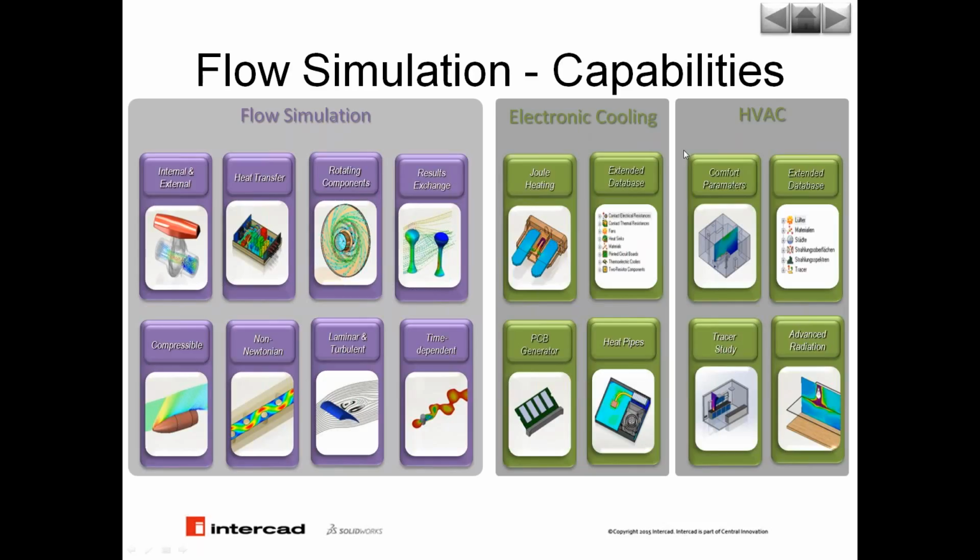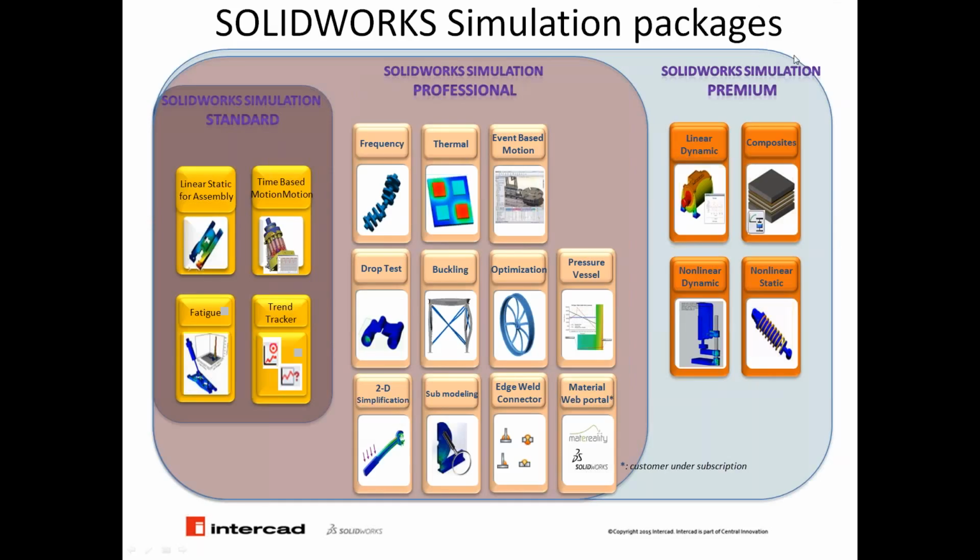And doing any study of this can be simply linked to our FEA package as well, where you have your CAD parameter, you have the flow study, and we do have the structural response here. Well, you can either use linear static studies or the capabilities of professional as frequency, thermal, buckling, or drop tests, or also accessing linear or nonlinear dynamic studies here.